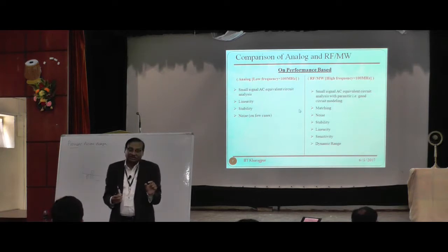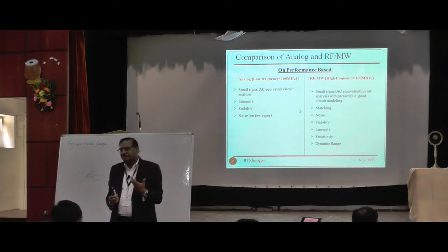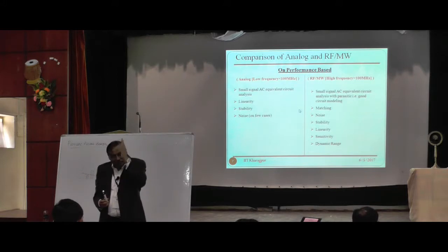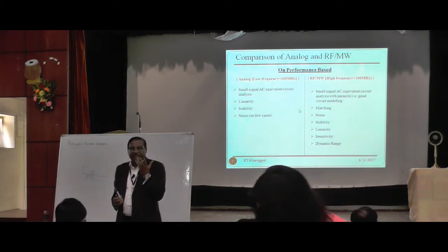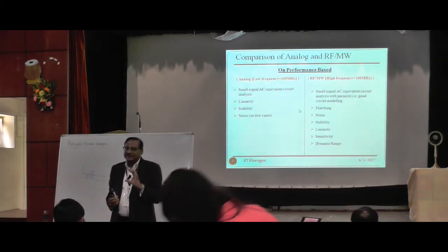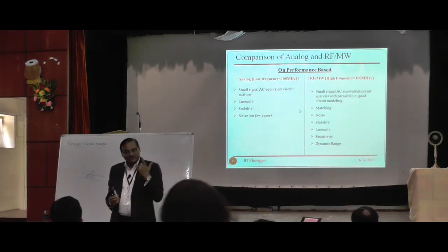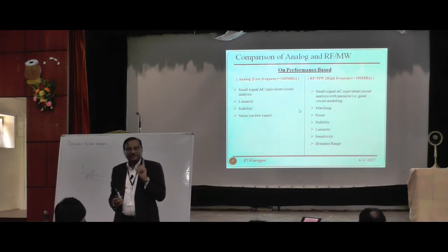But you can select only your channel by this matching network, which is also acting as a tuning network. What is that? The resonant frequency of that matching network should be equal to your desired frequency range. Clear? So it has got a dual role. A matching network acts as a tuning circuit as well as the matching of impedance transformations.